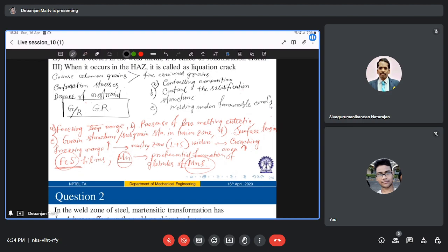Now by reducing the grain size, any potentially detrimental microsegregation or some low melting phase or constituent is basically spreading across more grain boundary area, and that might reduce the level of segregate to below some threshold level, which can cause this continuous liquid formation, and thereby prevents the cracking. Okay.